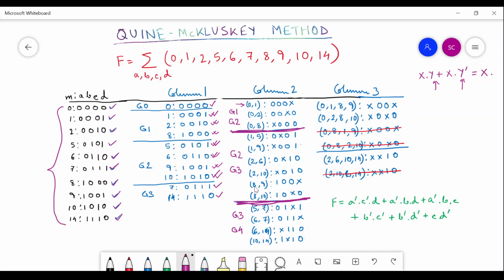So you see only 8 and 9 can match, and you now check whether only one bit is changing between the rest of the bits. So you see 0 0 0 and 1 0 0. So yes, one bit is changing, which is the MSB. So now you combine 0 1 8 9 and write them as x00x. Okay, no other combinations for 0 1 are possible. So also put the tick mark.